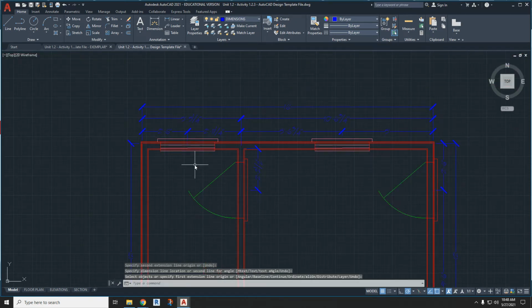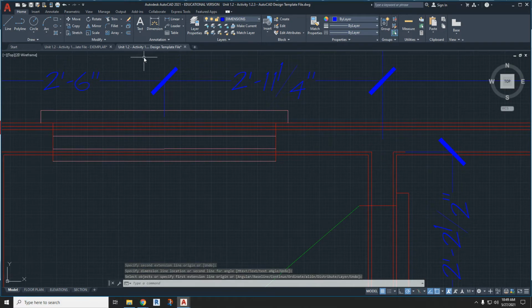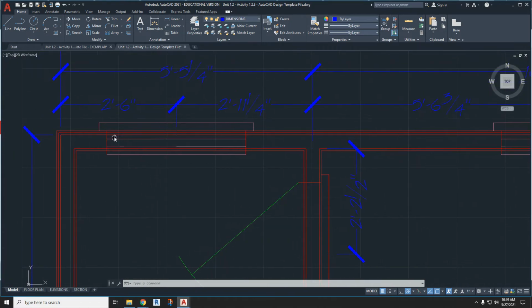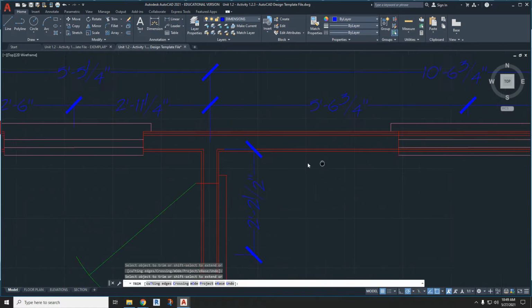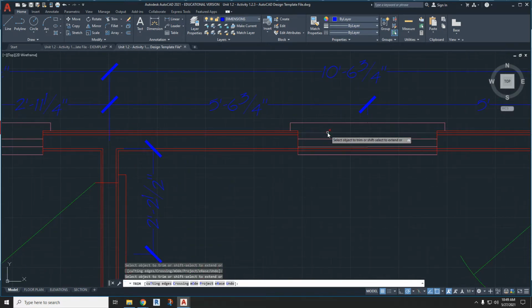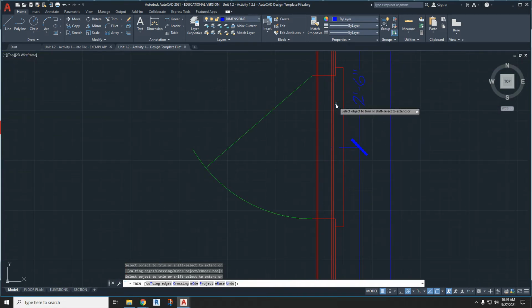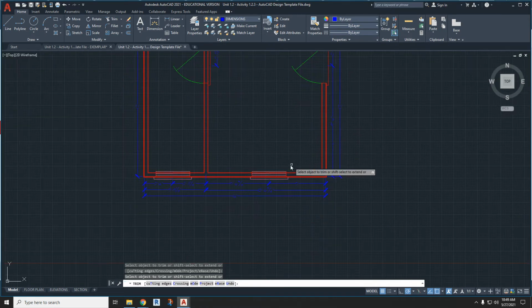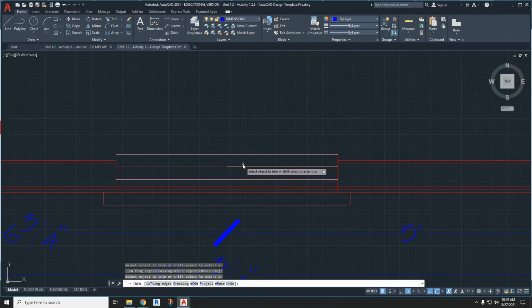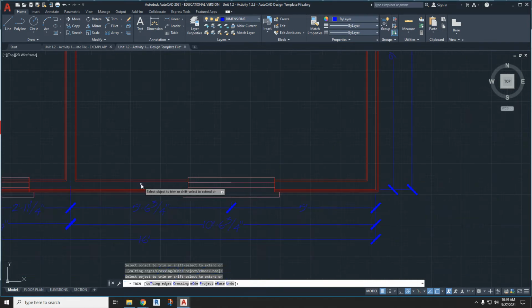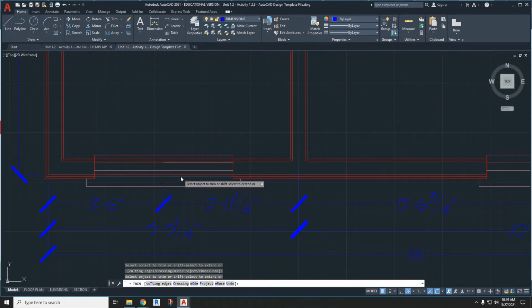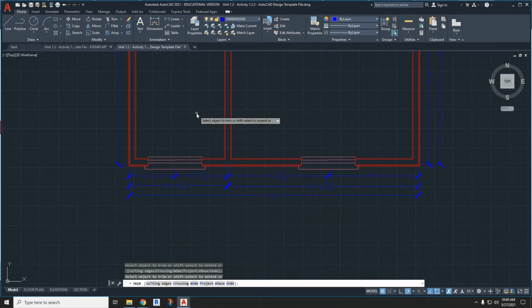All right. Now I got to trim away all this wall stuff that's in the middle of these rough openings. So hit the trim command. Trim away all this stuff, just the red stuff, not the pinkish for the window. The red is all the walls that, yeah, there we go. Because the walls, remember, are either cut or not built where doors and windows are, so it wouldn't make sense to have them there. All right.